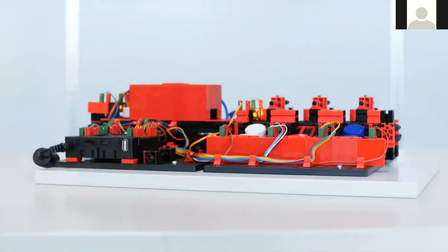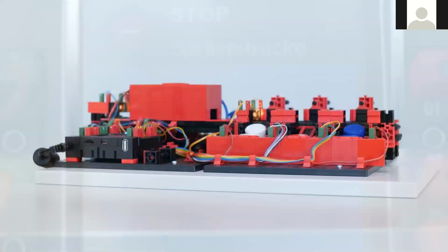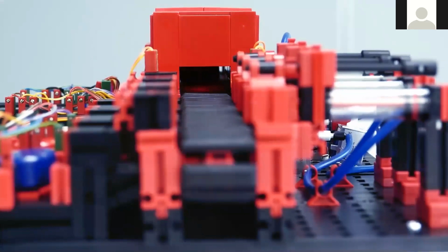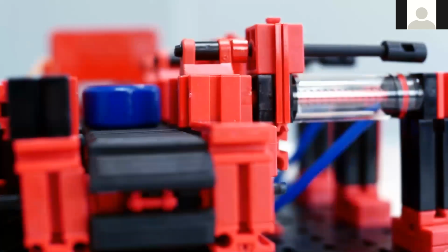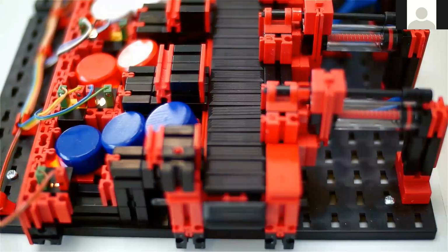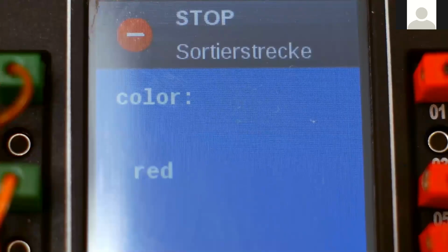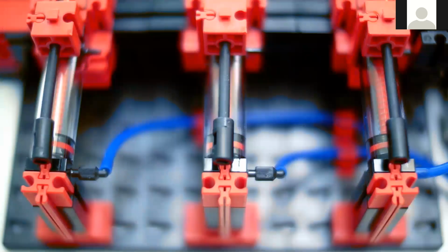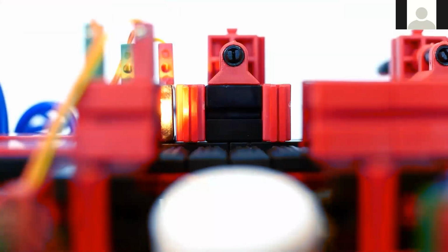The dimensions for this model are approximately 20 by 14 by 12 inches, and it has a weight of about 10 pounds. Now, as with the models we've looked at before, the standard 24-volt version has a relay board for motor polarity reversal and both a multi-pin connector, 34 pins with a grid of 2.54 millimeters, as well as additional PCB terminals with push-in connections for all inputs and outputs. Again, you will need to provide your own PLC and the programming. The limited edition 9-volt version, again, comes pre-wired to a pre-programmed TXT controller, and one 120-volt power adapter is required.